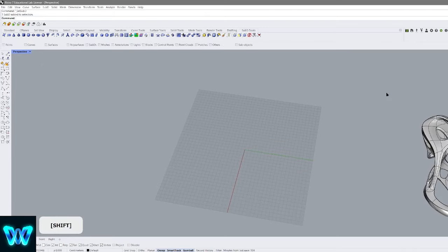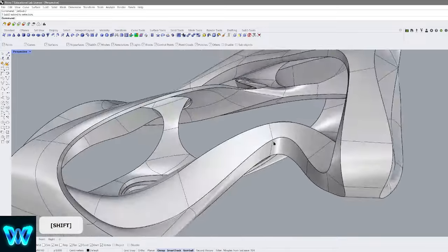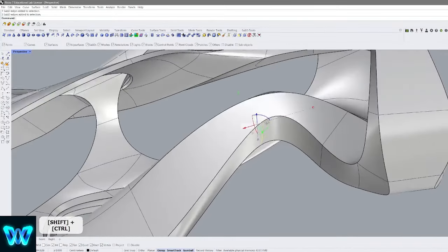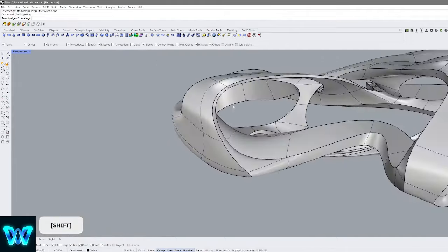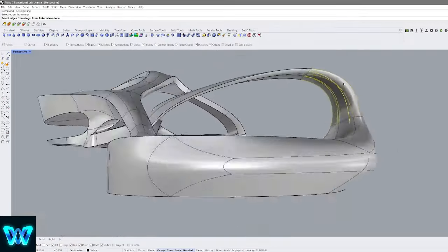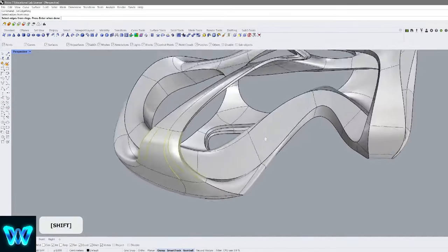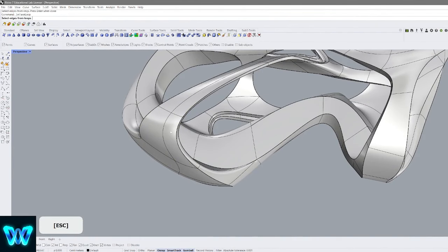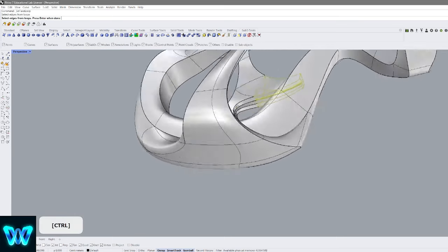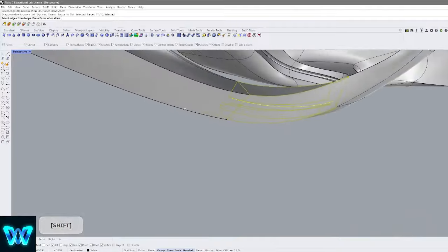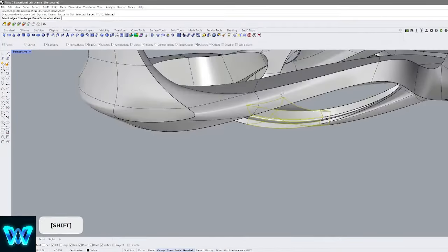Same thing here, you can select an edge loop. This is just the commands that I mentioned before, so if I just double click it, I can do that. But at the same time, I can just click here and it will select the edge loop for me, right? Same thing, you can select the edge ring. So you can click on select edge ring and it will select the whole ring that's wrapping around that set of faces. And same thing for faces. Select edges, this one, where you can select the entire thing even with the faces, so you can edit it.